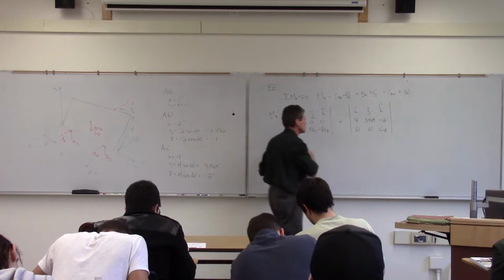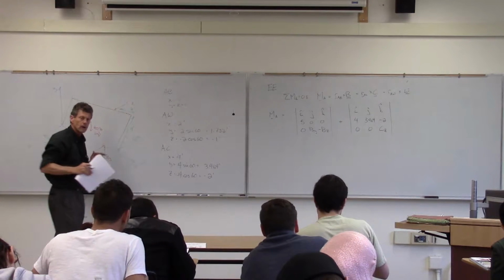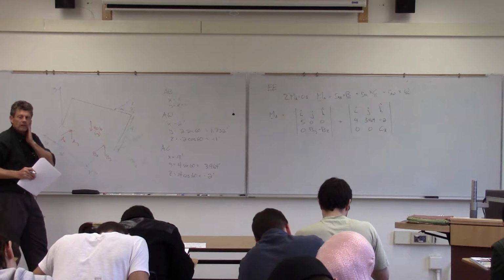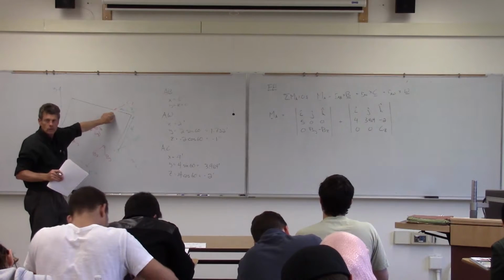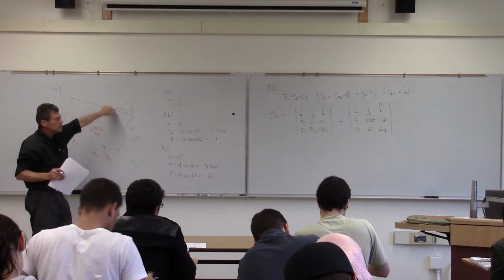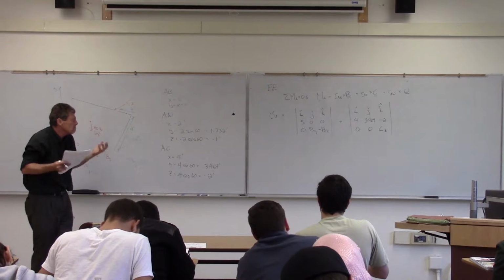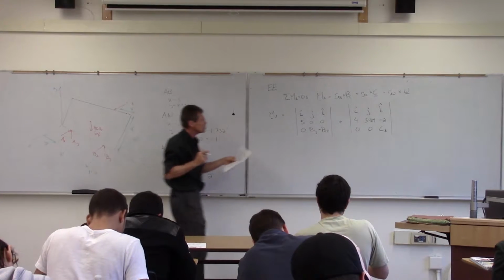It's got a few more things in the position vector there because I've moved over 4, and then I've gone up a little bit, and I've gone over in the negative z direction. But the nice thing is when I look at my component of my force there, knowing that's a smooth bar, I'm going to have only force in that perpendicular direction. So I have lots of zeros again in my determinant.